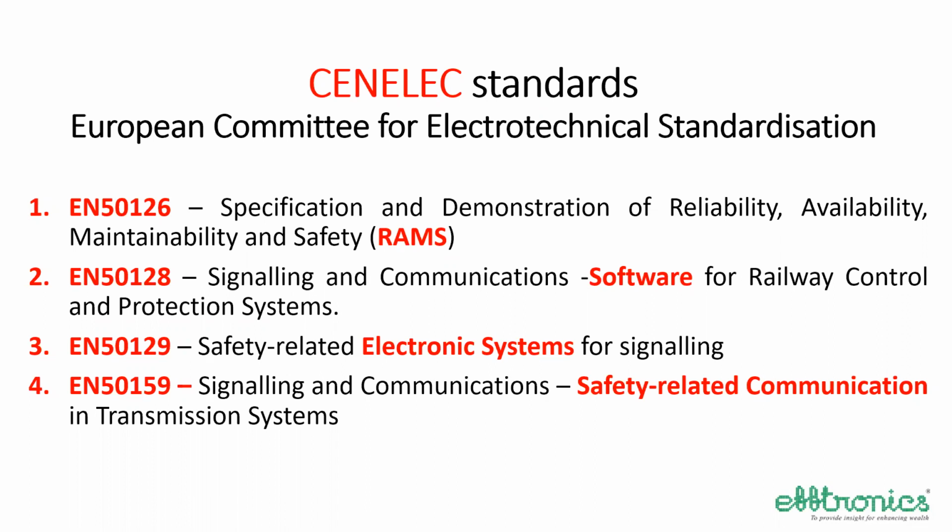Mr. Jagdish has acknowledged a very good seminar, very good information, sir. And is there any separate distance between transmission coil and the receiver coil, by Prem Narayan? See, transmitter coil and receiver coil, there is not much of a choice actually, because it is fixed to either side of the rail, and if you increase the distance, it becomes a problem for the maintenance of the track as well. So each manufacturer decides it in such a way that the proper signal is induced in the receiver. That is the criteria basically when you are using receiver and transmitter on both the sides.